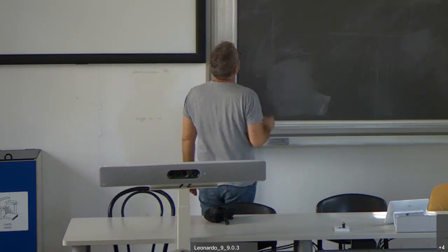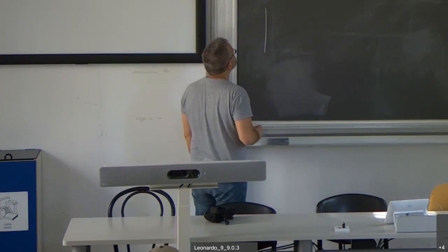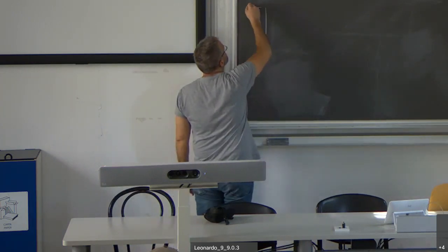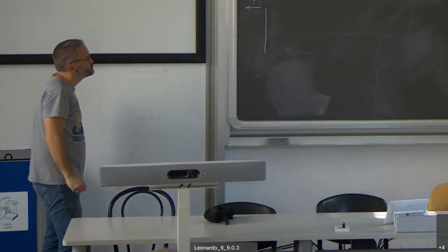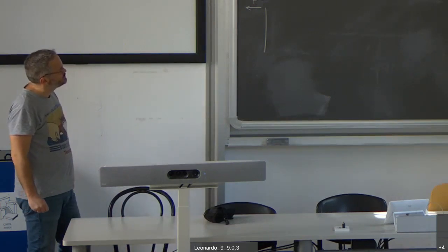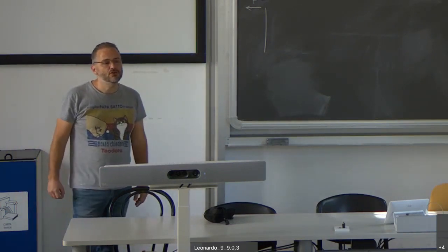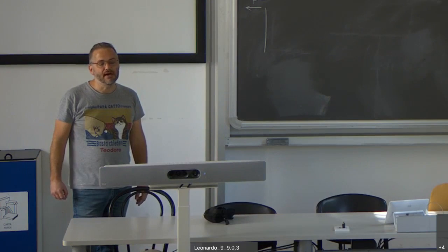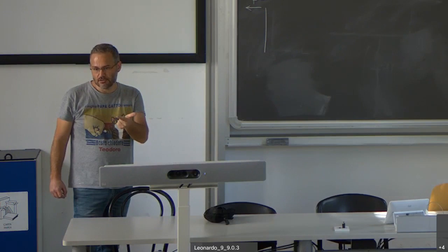So I start off at the top. PL. What are the notable points I use to work out my internal forces? Again, axial force will be constant or zero. Shear force will be constant or zero.